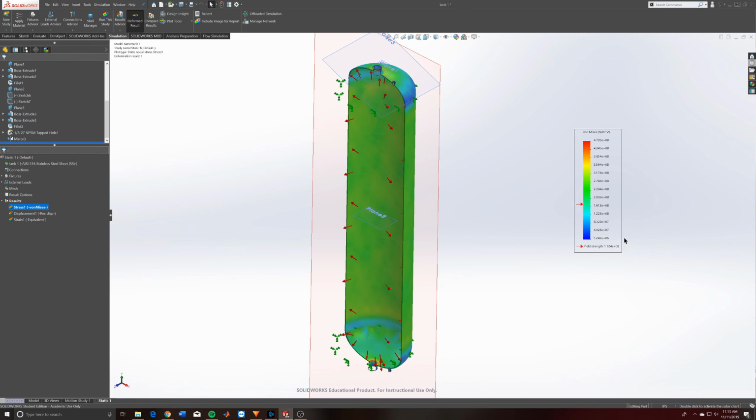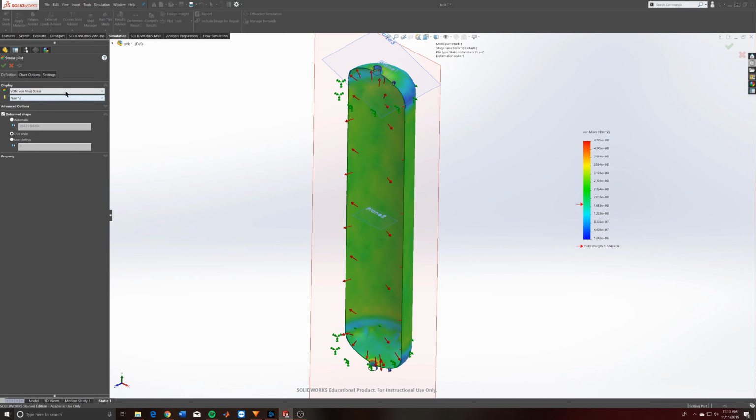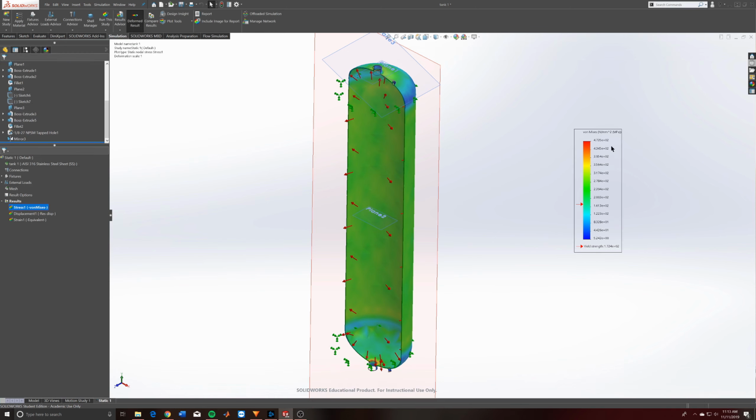You know what? I'm going to edit this. So now here we go. These are MPa. Yeah, so 172 MPa. It's right around here. So anywhere you're seeing this light teal turning into a green color, that means the material is actually yielding. So anywhere down here, in here, up in here as well, and around the holes.